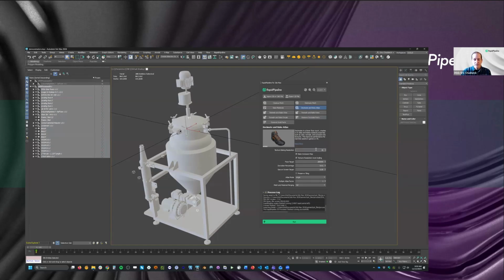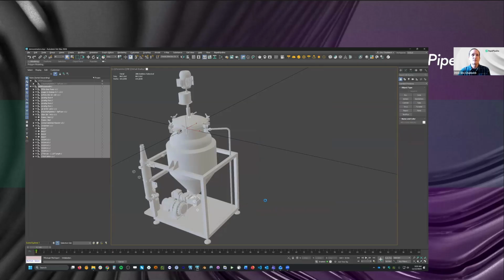I'm going to choose a little bit higher texture resolution because there's so much detail in this model. And when I bake the occlusion map, I'm probably going to need that extra detail. I'm still going to collapse it down to a full. One thing you can do too is in this particular asset, there are a ton of materials in this scene, and there are a ton of objects. There are like 386 entities. And I know that there are 22 materials in this scene. That'll bake it down to 22 objects, which means then by material, each of those objects are visible. So let's try that and just see how that works.